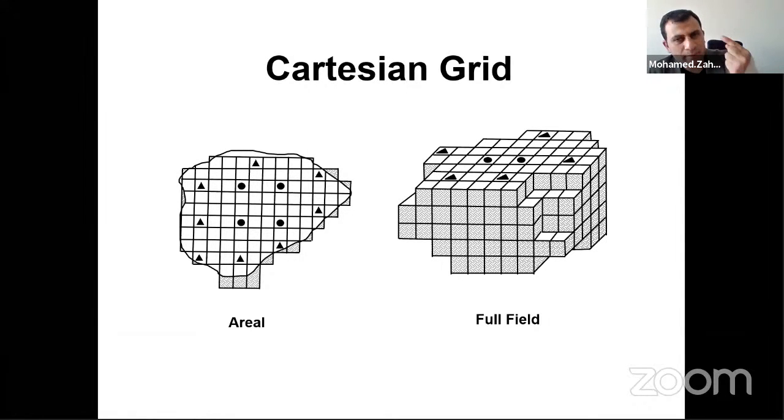I will repeat it in English. If I'm going to calculate the diffusivity equation for my reservoir, which is 3 dimension, I have to split my reservoir into very small, tiny grids, so that I can calculate for each grid the pressure and saturation, permeability, porosity, and net porosity. So that's what I'm calling the grids. The big reservoir will be divided into small grids. Those grids will cover the x dimension, the y dimension, and z dimension.